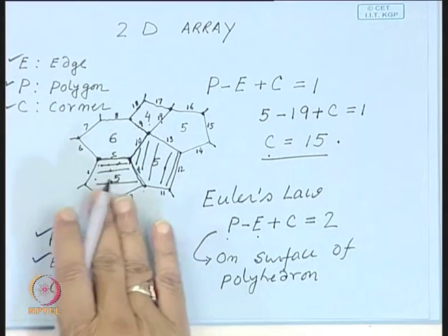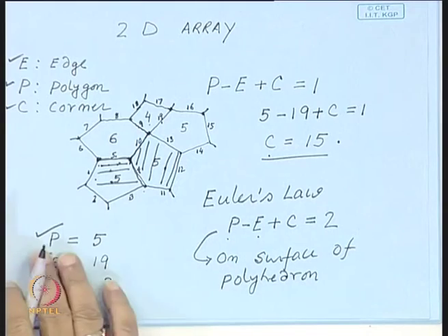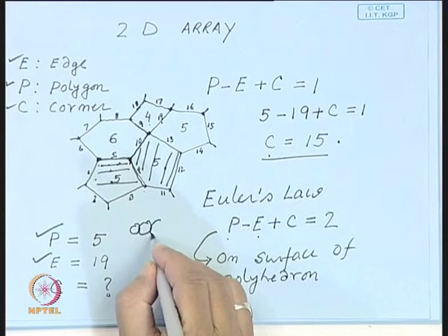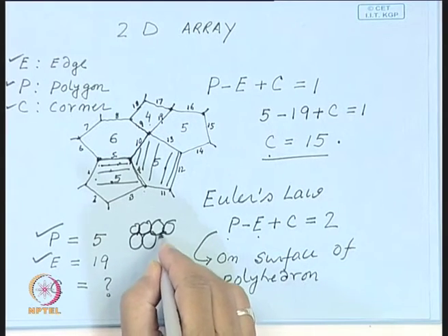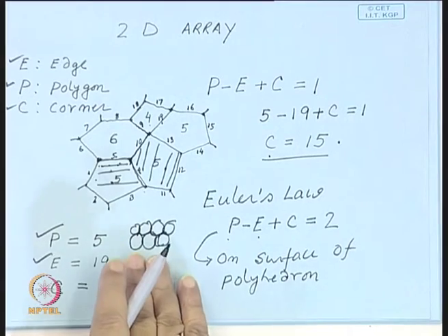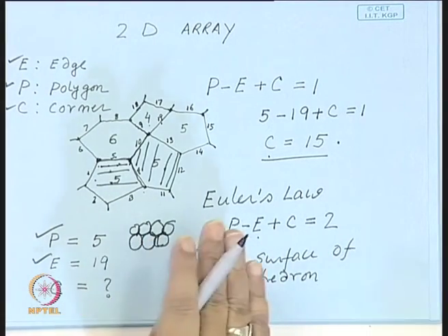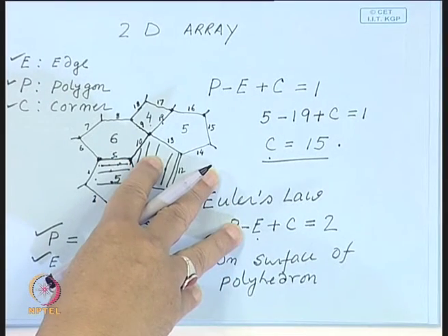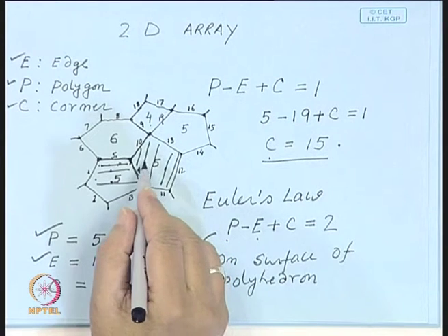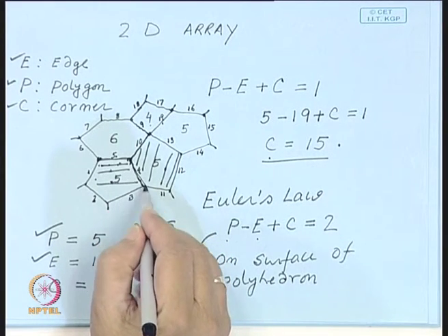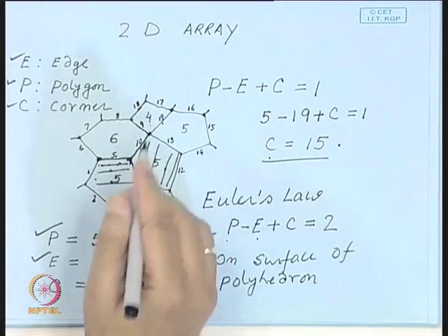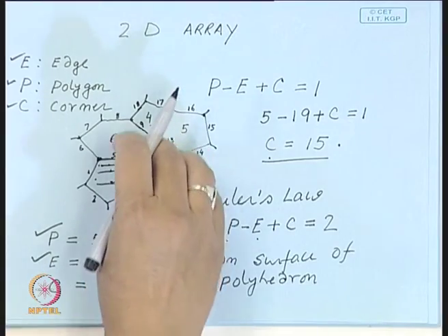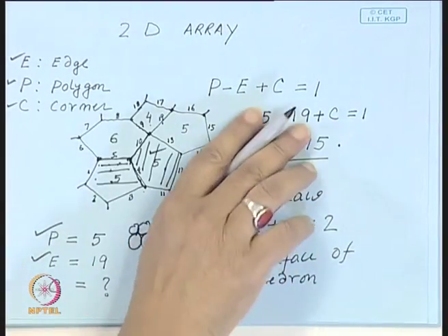You can do it as an exercise, and on a piece of paper, if you can take a transparent sheet and draw this atomic array at a regular interval. Maybe you take that close packed plane, you draw this close packed plane like atomic array, one sheet, and you take a Xerox copy of that on another sheet, and now on that transparent sheet you put on that and try and rotate through certain angle. And that means what you are doing, you are trying to visualize what is the nature of array near the grain boundary. So, maybe part of it you say this, that means you can generate this atomic array by rotating this grain.